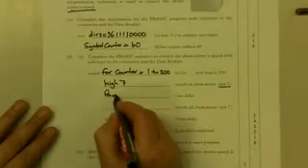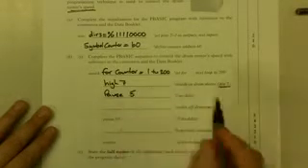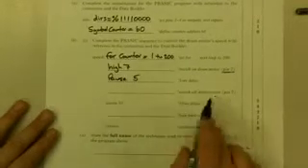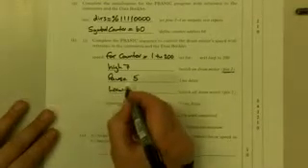5 millisecond delay, so it has to be a pause 5, and then switch off drum motor, low 7. Then you've got another delay, so we've got a ratio between the amount of time it's on and off, and then loop until completed. So you could put next B0, or you could put next counter, it's the same thing, and then return at the end of the program.